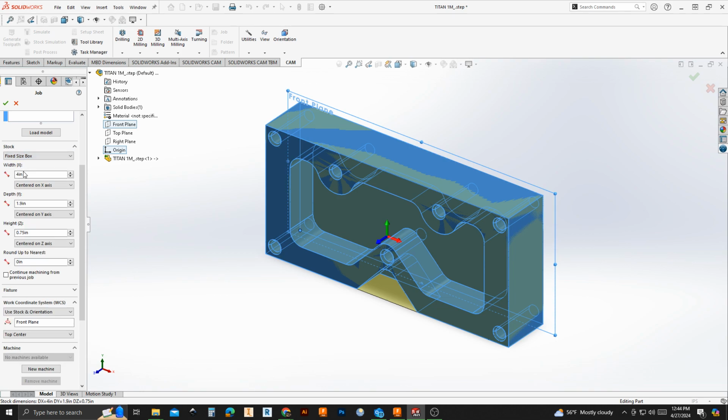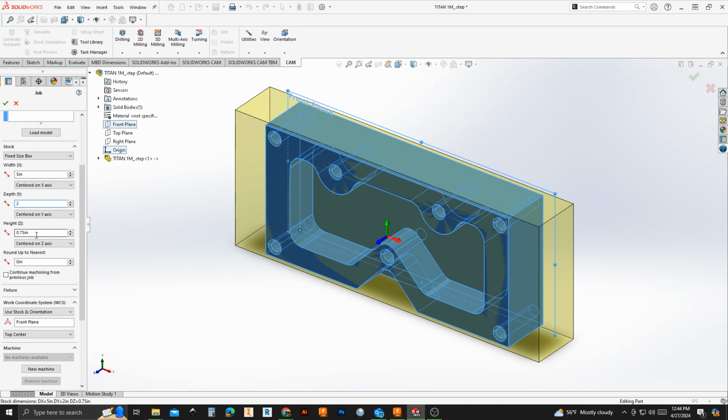This material should fit your material that you're going to be holding in your hand that you'll be sticking in the mill. So you will actually need to measure that material or know what that is. And this is something you can come back and change later. So right now I'm going to give us a little bit of leeway here. We're going to say it's 5 inches long and 2 inches wide and 3/4 of an inch thick.